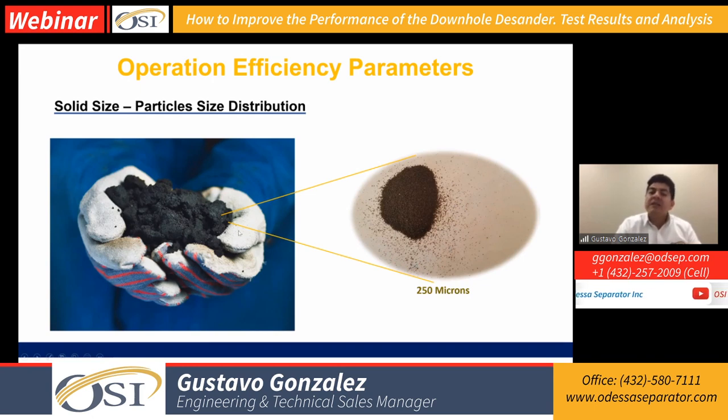In this case, I use a combination with the two-stage filtration, as we call it, which is what we mentioned before: having the opportunity to have the screen as an intake and not just a slotted one. We're going to see a higher efficiency because I am delaying the time for all this sand, or the chunks of sand, to go inside the system. I am giving more opportunity to increase the fluid velocity internally and allow the helix to better handle the particles when they are passing through the vanes.